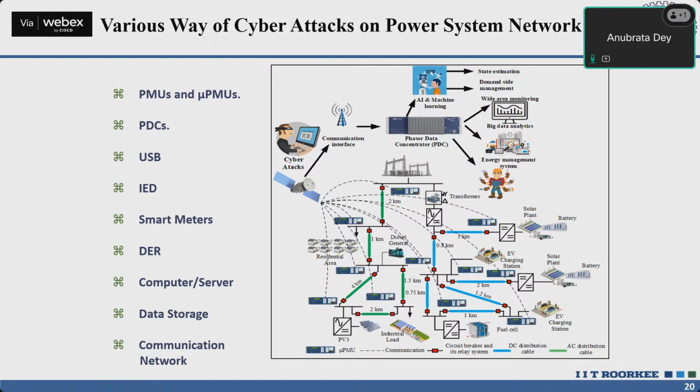Let's say if one company is there, for example, our IIT Roorkee, we have a contract demand of 1 megawatt. So for 1 megawatt, per kVA, whatever amount is fixed by IIT Roorkee and the utility, UPCL in our case, Uttarakhand Power Corporation Limited, that amount is fixed. Let's say per kVA 5 rupees or 10 rupees, multiplied by 1 megawatt converted to kVA.